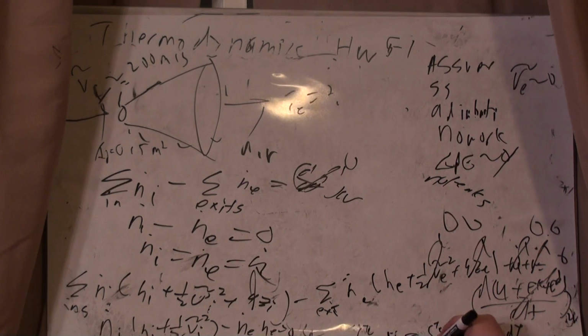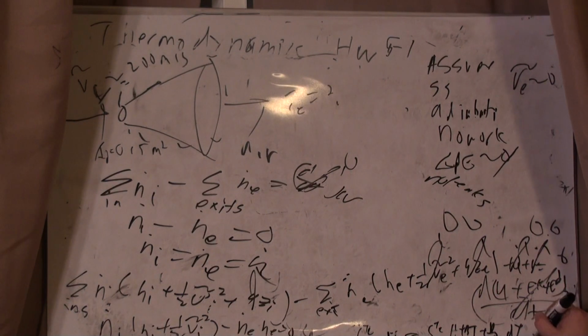Do that integral, I have A times (T exit minus T in) plus B over 2 times (T exit squared minus T inlet squared), minus D times (1 over T exit minus 1 over T inlet), all times R. Okay, all that's equal to 1/2 v squared in.